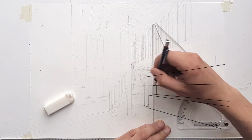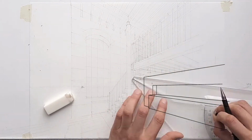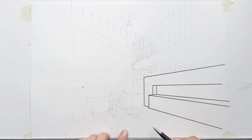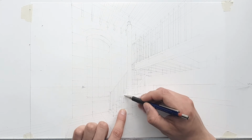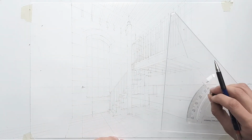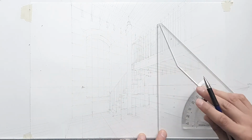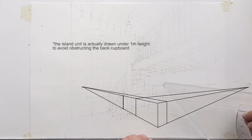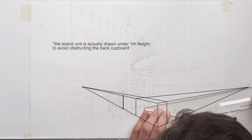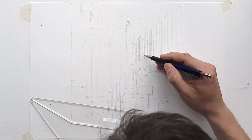The shelving above is 40 centimeters deep, which is less deep than the counter underneath, which, as you remember, was 1.5 increments, so the corner is defined. This next bit, I'm drawing a box for the island unit. Again, the height for that at 1 meter, I'm getting from the back wall basically and projecting it towards the island unit markings that we previously did.